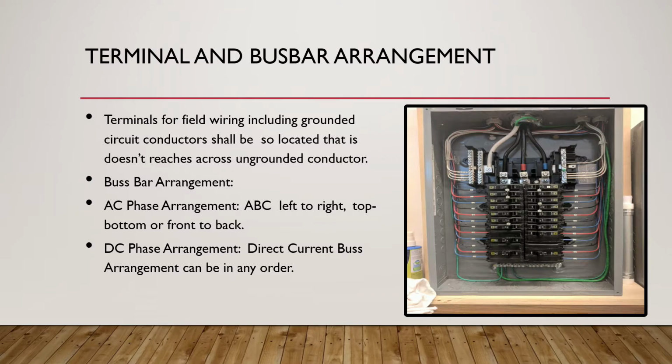So looking at the terminals, or the bus bar, in this diagram here, we are not able to see a bus bar being exposed, but yet we have the terminals. So if you notice how they're arranged, they're clearly not crossing each other as much as close as they may be. They're in a designated position. So you have the red, the black, blue, and the red, all in their designated locations, and that is followed by the neutral.